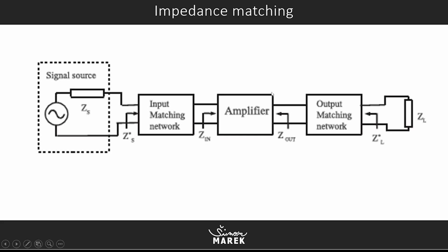So here is our amplifier, and for LNA, oftentimes they're internally matched, so you won't require any input matching network. All you need to do is really put your amplifier and put your DC block capacitor or coupling capacitor in series, and you don't really have to care about input matching network because it's internally matched for 50 ohms.